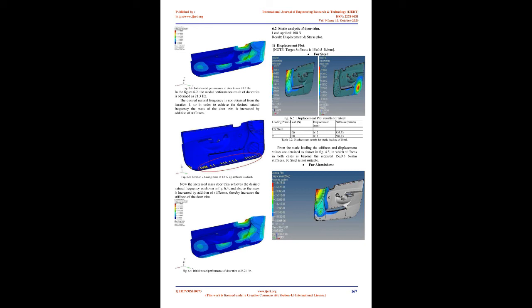Maximum angle: if the obtuse angle between two edges in a quad element is more than the limit, it will not be accepted by the software. Minimum angle: the angle between two edges in a quadrilateral is less than the limit. Aspect ratio: the ratio of maximum length to minimum length should be less than the limit. Jacobian: the differential matrix obtained from the stiffness formulation is called the Jacobian.